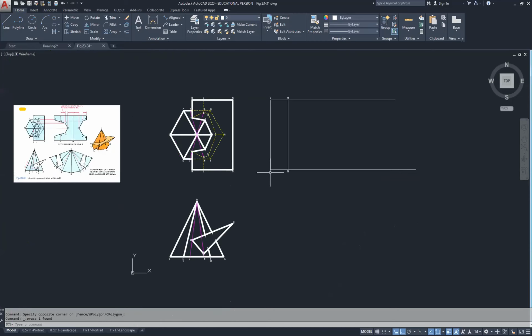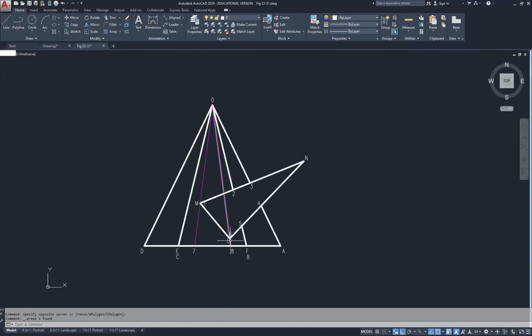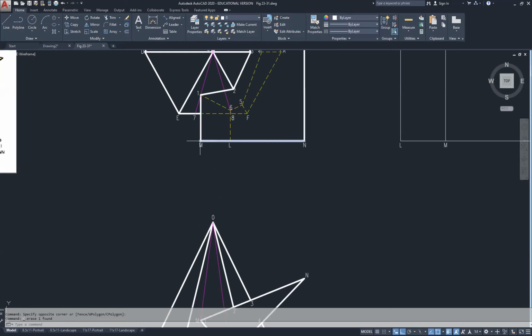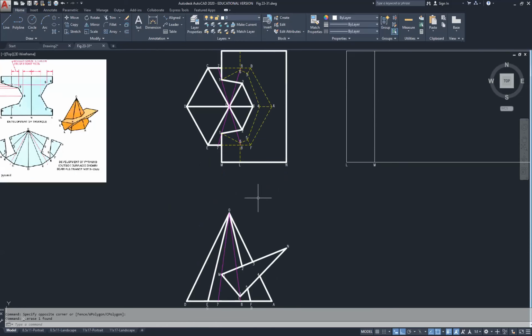All right, so the distance from L to M is now the same distance from L to M here. You'll notice on this view, L to M is foreshortened. And that's why this view is untrue. But this is true. And notice that it's straight instead of on the angle. That's one key factor of wanting to lay it flat.